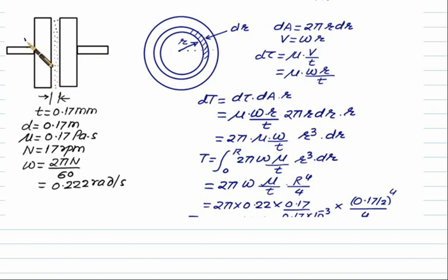Suppose it is rotating with a speed equal to n1. Since we don't have a positive drive here, the power is transmitted by means of fluid. This speed will be equal to n2. So if we hold the n2, in that case the fluid will get sheared by the difference of the velocity equal to n1 minus n2. So that is the relative speed. Now this concept can again be solved: how much power will be wasted in overcoming the friction, or how much torque is required to overcome the friction.